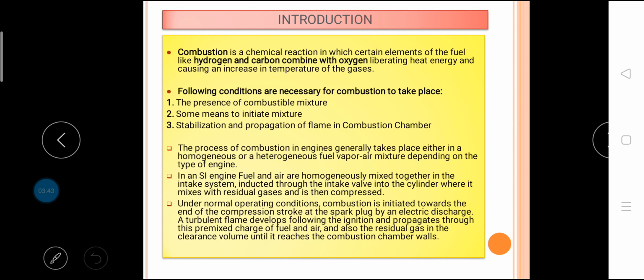When the mixture is heterogeneous, the combustion can take place in an overall lean mixture since there are always local zones where equivalence ratio varies between 1.0 and 1.2 corresponding to maximum rate of chemical reaction. Ignition starts in this zone and the flame produced helps to burn the fuel in the adjoining zones where the mixture is leaner. Similarly, in the zones where the mixture is rich, the combustion occurs because of the high temperature produced due to combustion initiated in the zones where equivalence ratio is 1.0 to 1.2.